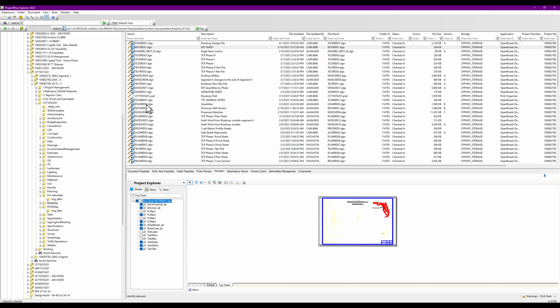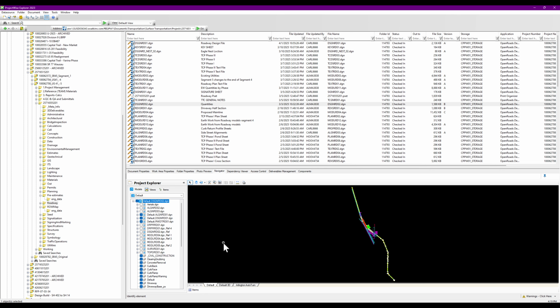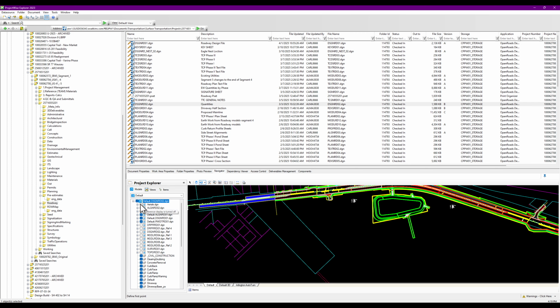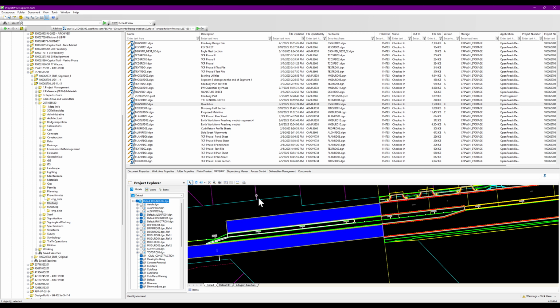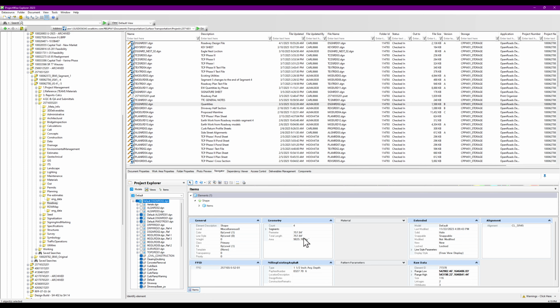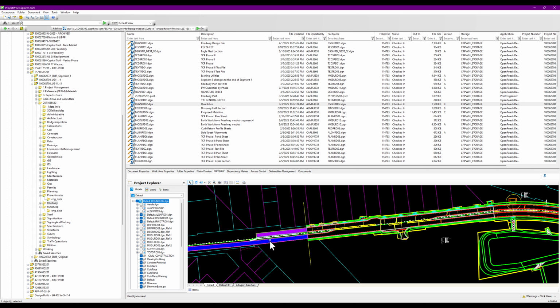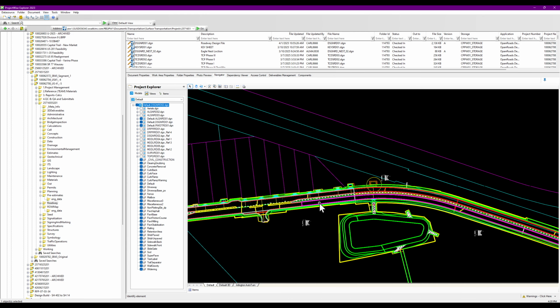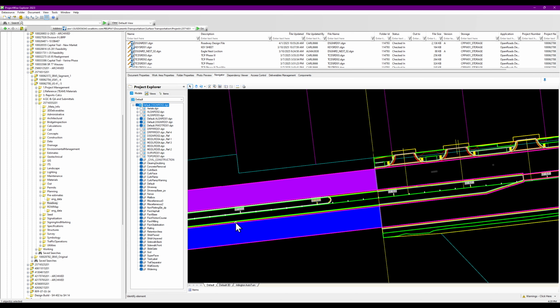Let's go to a design file, because for example, let's see, well, before we do that, let's do the quantity file. This file is a quantity file, and inside this file we have shapes that have quantities. And we have this model here. So let me rotate. And then I have a lot of them here. So let me click on this. This shape, I know that they told me this is supposed to be the existing milling shape. So if I click on it and I click on items, I get to see actually the geometry of it. And I get to see that you have the pay item that is already coded to it. So this will be good for people who are doing QC and for the estimated quantity report, which is the EQR for short. Instead of actually opening the DGN, you can just go to the Navigator, go to the models that the people who did that, and you can check them. You can check exactly what's inside them without the need of opening the DGN itself.